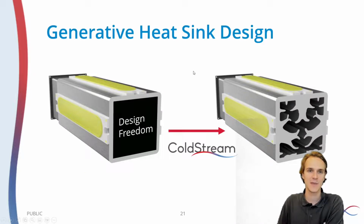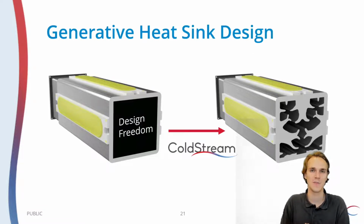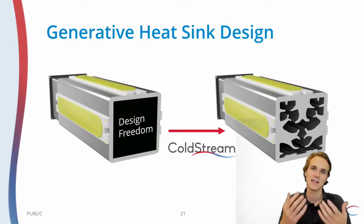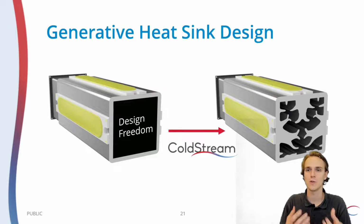All right, and so how using ColdStream for generative design differs from the thermal analysis that I just showed you is essentially there's only one new thing. It is the design space that you have to define. And so essentially, in addition to the air volume that you model, you also have to include a subregion that defines the design freedom that ColdStream has to decide, would I like to place structures or not?